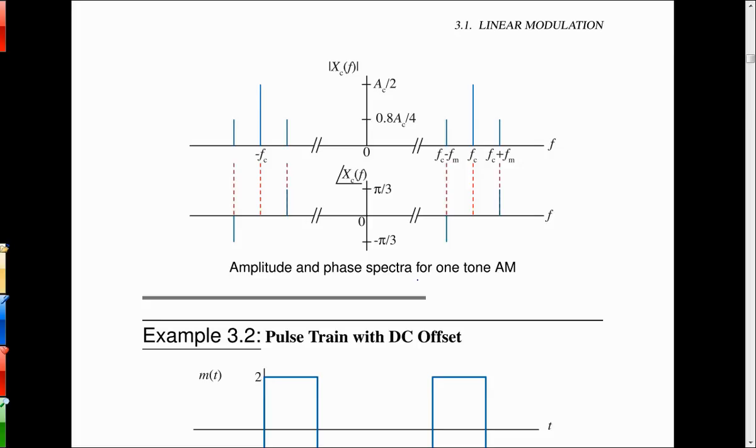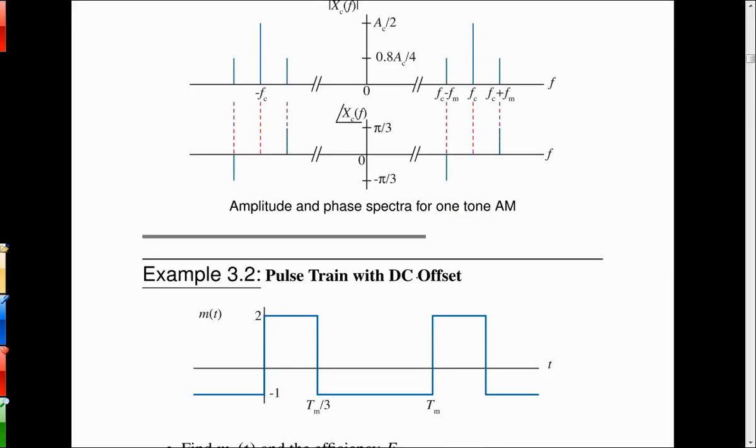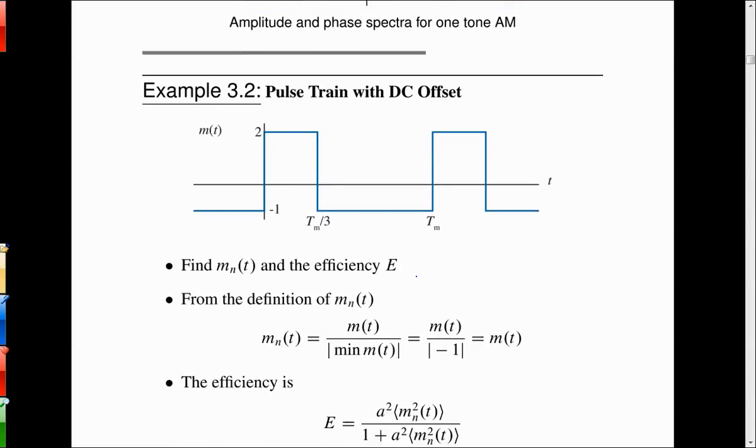It's kind of like if you were getting beat over the head with the carrier, you'd say, where's the message? I can't tell because the carrier is so powerful, but in the demodulator, the carrier is just that DC bias that comes out of the envelope detector, so it's not music or anything. You'd remove that with AC coupling and the electronics. There are certain types of signals that can get higher efficiency, like the pulse train, for example.